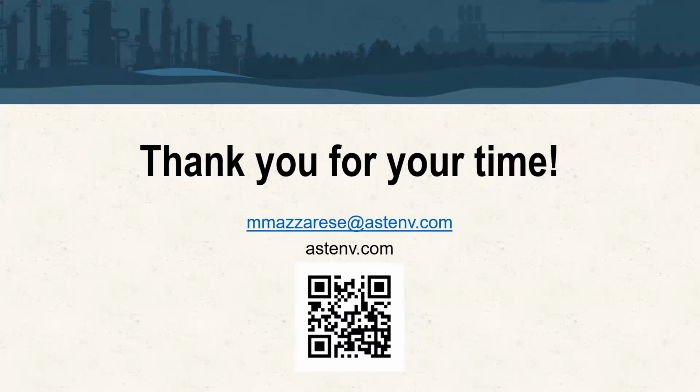Those of you that have sat in on other webinars where we've highlighted our geotap or pre-drill technique: we've done a number of sites where we've pre-bored with sonic or augers to get into weathered bedrock. Because we're injecting slurries, we can pressure inject through the bentonite that we can place in that hole. So I would say more in transition zones than bedrock, but we've done more Boss 100 work in bedrock to date.